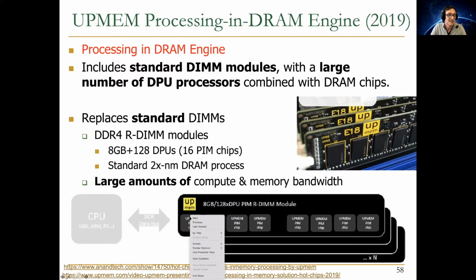Simple processors. And they're not extremely capable because the process technologies that you use to design memory chips, main memory chips, and processors are actually not as compatible. So these folks actually did that. Now you can actually do the processing next to the data without moving the data outside the DRAM chip. Now, this is great because moving the data outside the DRAM chip actually costs a lot of energy and a lot of performance. So you can gain a lot of performance and energy back by minimizing the data movement. So this is actually very fascinating, in my opinion.